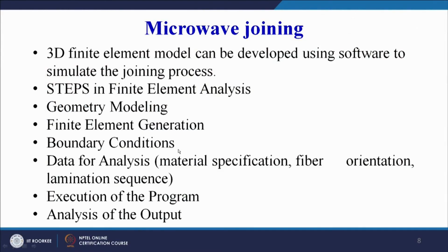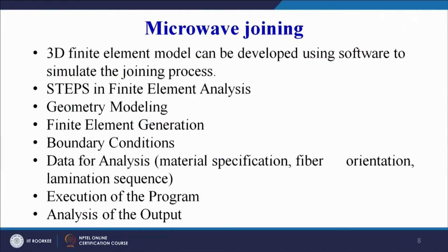Boundary conditions are applied, although now here we have to heat the joint area, so the boundary conditions will change, but the steps remain the same. Data for analysis is specified, we execute the program and then we analyze the output. So the basic finite element steps remain the same.